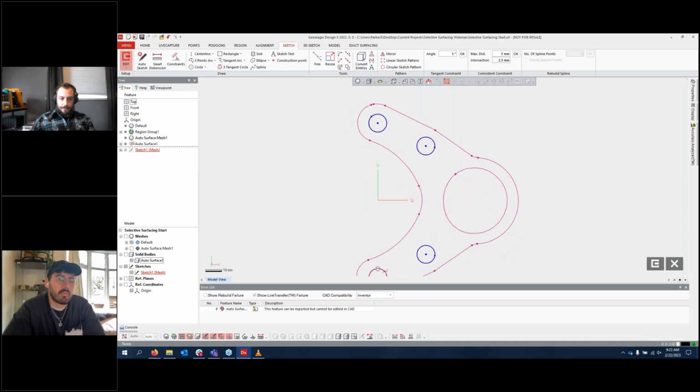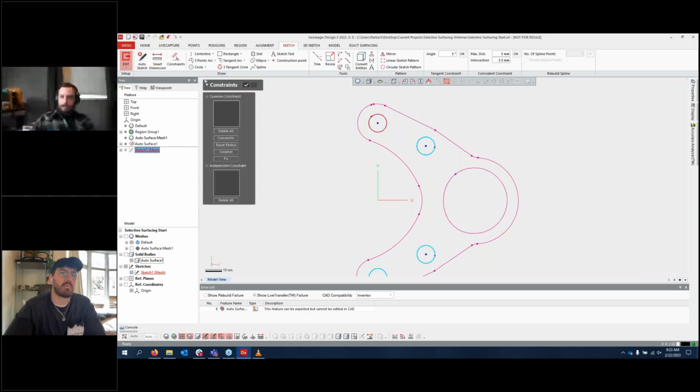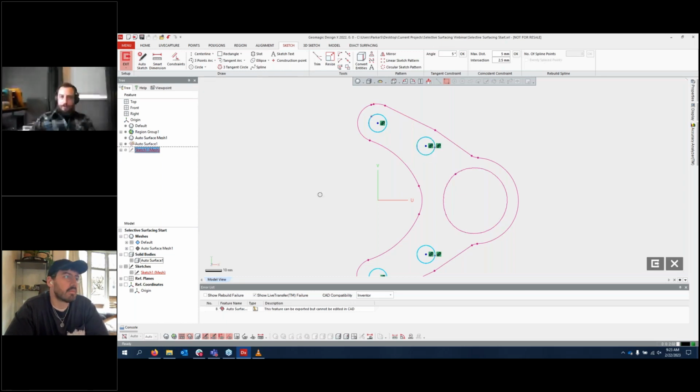And then of course, since this is Design X, and since we're probably going to go somewhere downstream to CAD, it's probably worth creating some constraints, right? So equal radius on all 4 of those holes if I want to constrain them that way. This is definitely something that we couldn't do if these holes had been auto-surfaced over. So that's one major benefit of working with feature modeling.